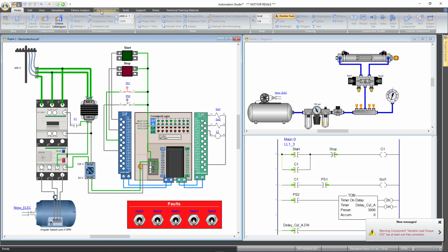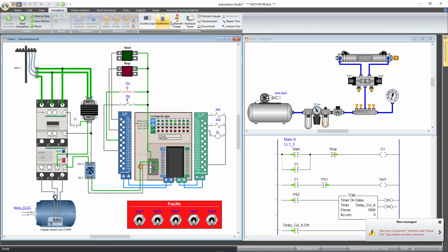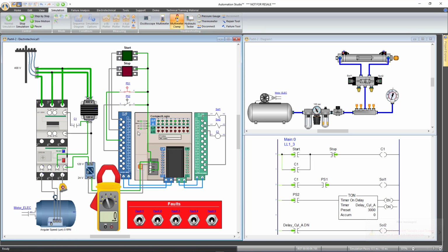let's take my amp meter now. This is going to be important. So right now if I go to amp and I measure the amp on the motor, if I do start, the current went up at the beginning and then it stabilized. And it's running now. Now, obviously, the motor you can adjust. I just use the motor that we have here, but you can set the starting current and things like that in your motor. That's not a problem, okay?